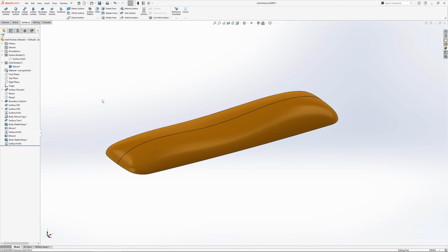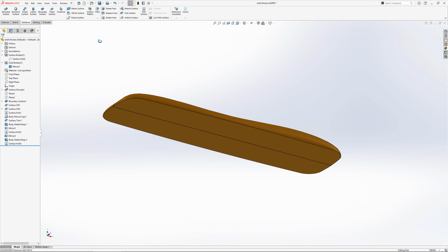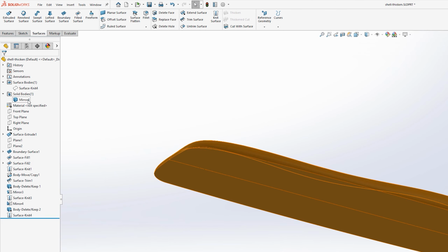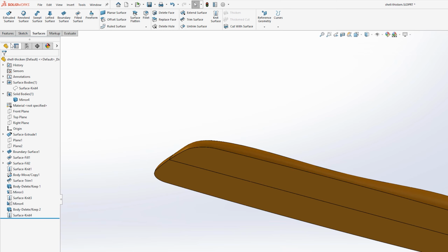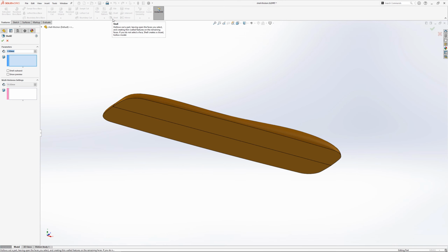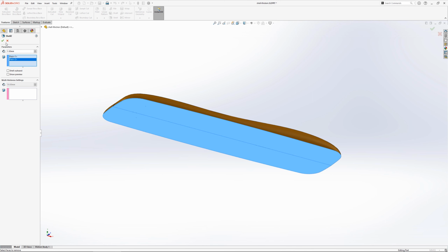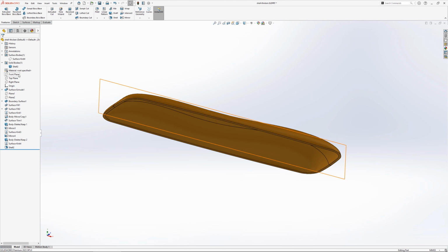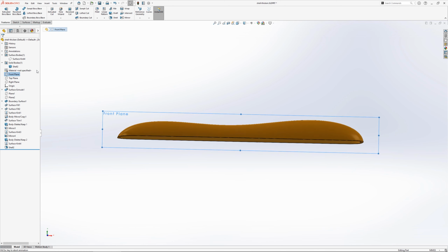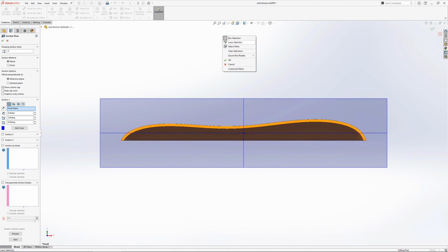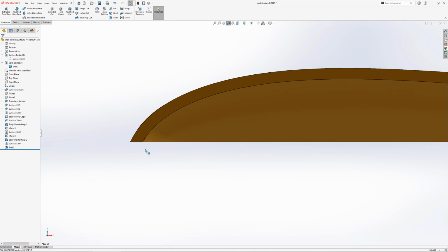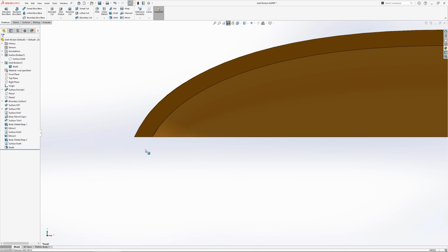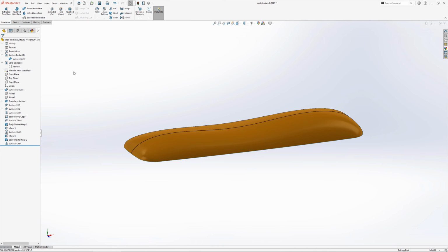Organic consumer products tend to be thin-walled, and there are two common methods when creating thin-walled parts: shelling and thickening. To shell a part, it must be a solid body. A single or multiple faces can be selected to be removed, with the remaining faces having the thickness applied to them either internally or externally. When the shell command is used, the faces across the thickness maintain the same orientation as the face that has been removed. Therefore, if there are any angles or curvature on specific faces, the shell thickness isn't applied at 90 degrees on those faces.